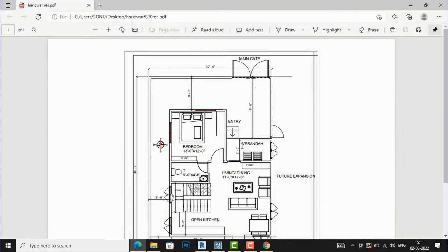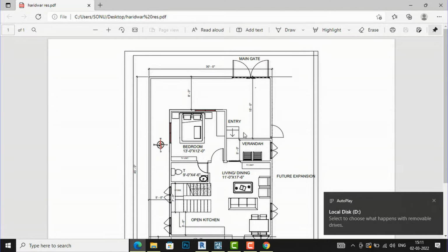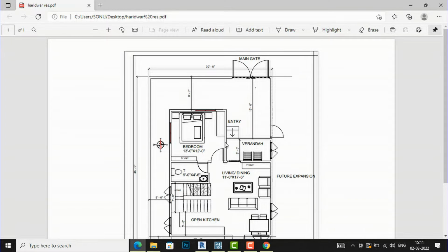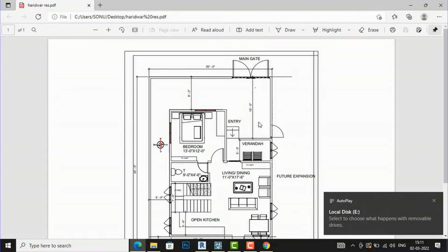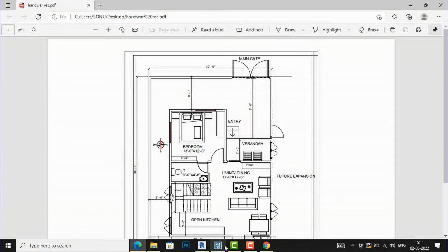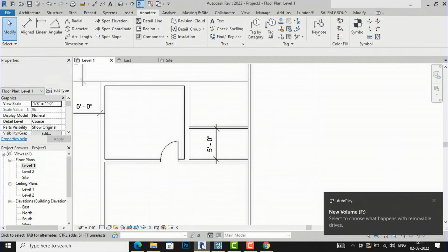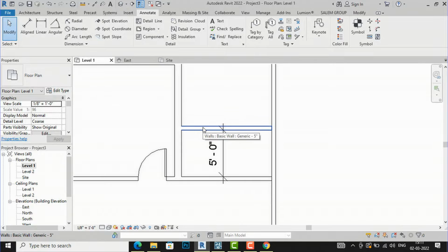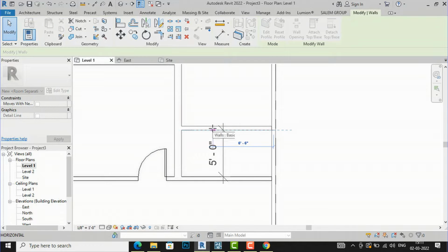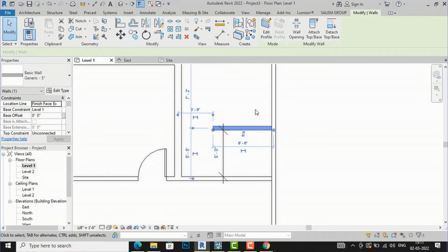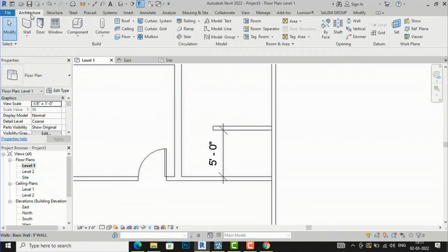So now you can give any opening. This is an open veranda, so there is no door. So first you need to draw some plinth stairs here. So this is as per your plinth height. So now I am going to first define this space here. So I am going to use stairs by sketch. So I am going to my architecture, and I will give this some opening here, open veranda. So I'm going to first go to architecture, and now I will go to stair here.